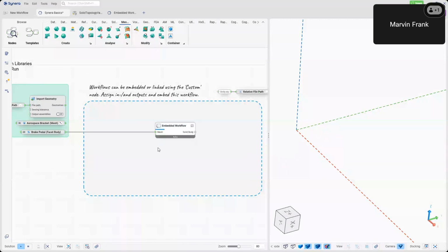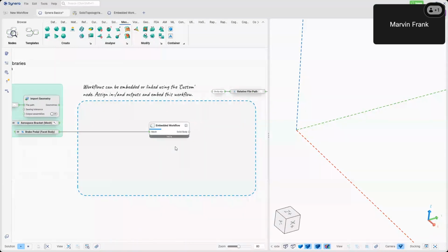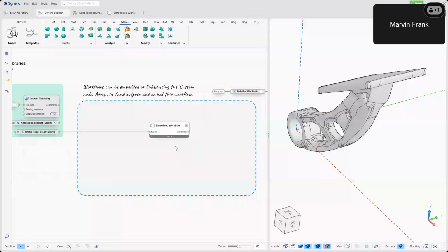If you deal with the automatic topology optimization result reconstruction, then you might run into several issues of it's not really robust. It's very bad mesh, for example, and there are certain cleanup options and ways, and they are also available as template. So just check out the templates. You will find at least 4 templates only about topology reconstruction. In this case, you see that it succeeded, and this workflow seems to be fine for both of the inputs.